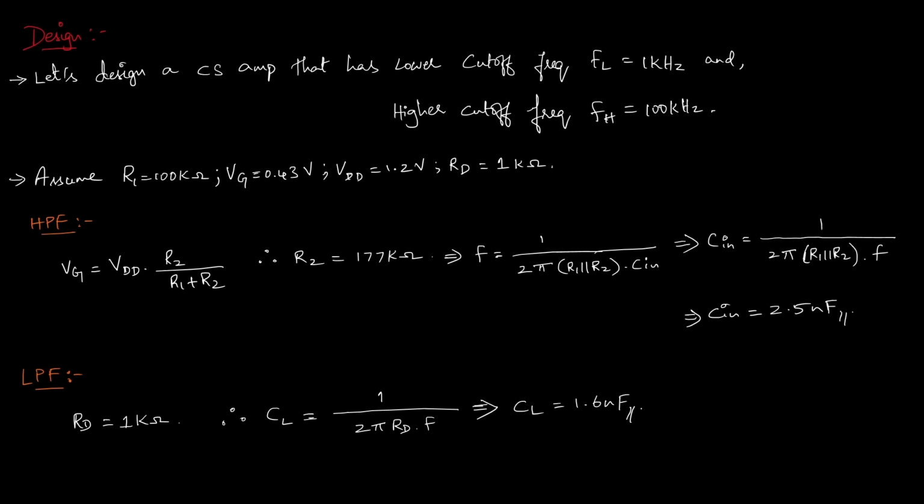The resistor RD occupies a lot of area and limits the achievable gain. So in the next video, we will take our first step towards active load and replace this resistor with something much smarter, the NMOS diode connected load. That single change will completely change how we design amplifiers in integrated circuits.